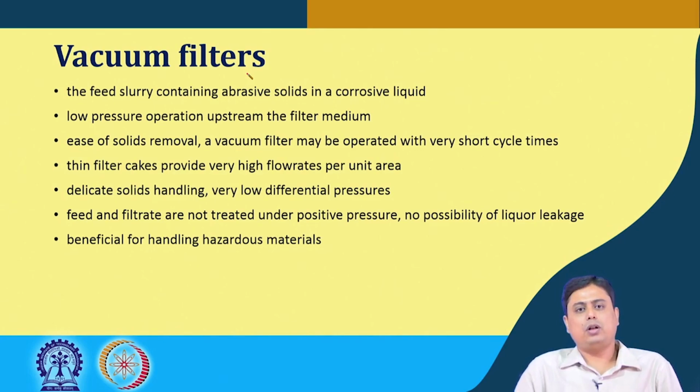Another advantage is the ease of solids removal, because the top surface of the filter media where the feed is coming is easily accessible. If there is a huge cake deposition within a short cycle, this can be quickly removed, and once it is removed, the thin layer of cake provides a very high flow rate per unit area of filtration.